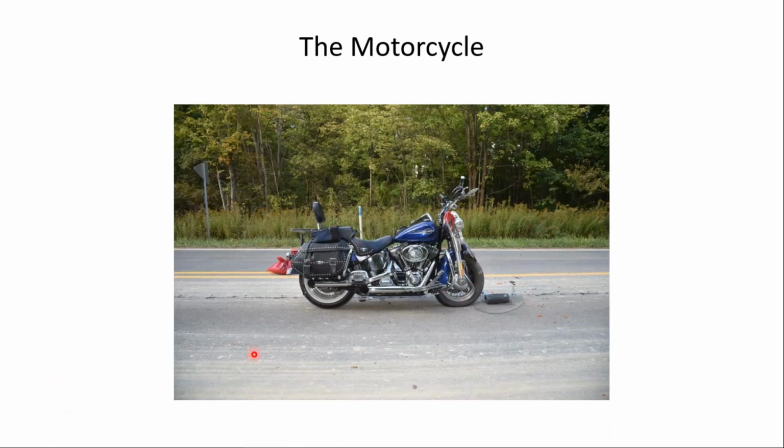One thing you'll note, especially those of you who are motorcycle operators, notice that that front fork has been compressed severely because this bike ran into the back of that skid steer. In the field of crash reconstruction, there are equations or curves or tables that, if you know the amount of compression of the fork and you know something about the stiffness of the bike, meaning the make and model of the motorcycle, you can estimate the impact speed of the bike at the time it struck whatever object it ran into.